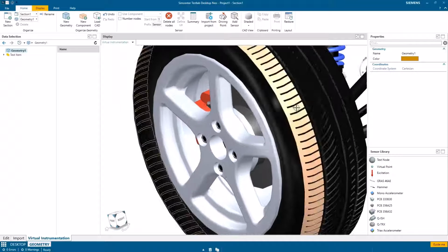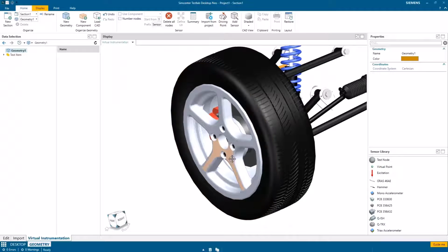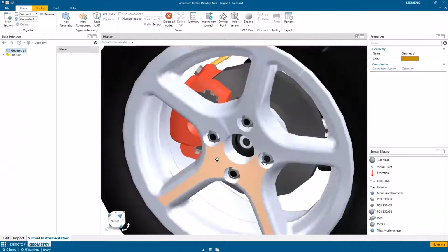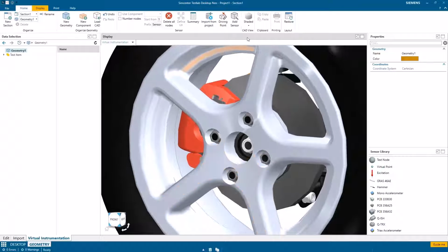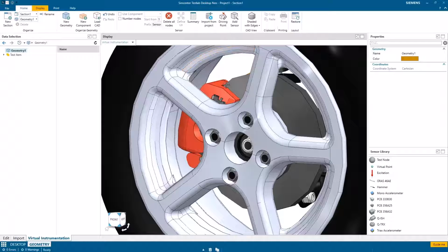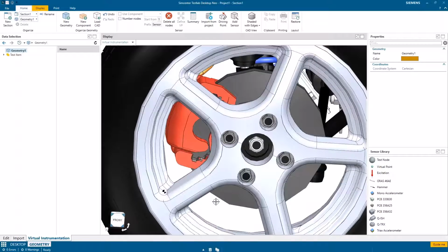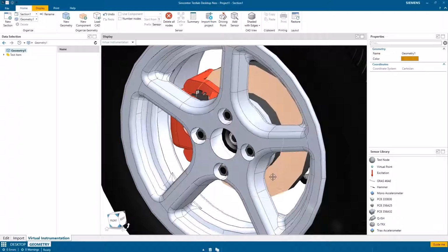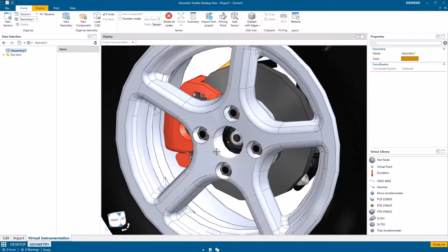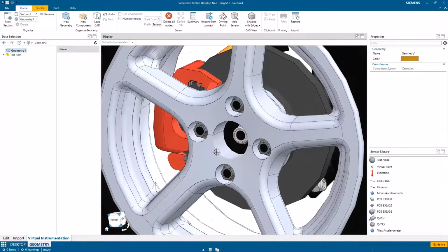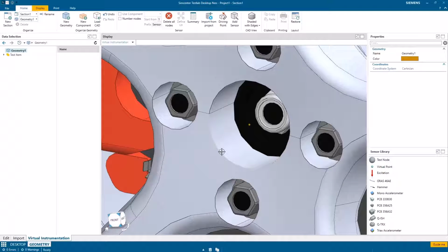So the first tip I have, if you have a .prt or a JT file format that started as CAD, you can use this shaded and add this shaded with edges. And that just puts some lines around the different geometrical features of the CAD model itself. And it will allow you to do things like, if I hover over this arc right here for this center hole, you see it suggests this center location. So this is the center of this hole here. That's the kind of stuff you get using the geometrical features.